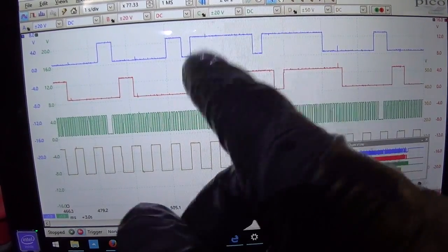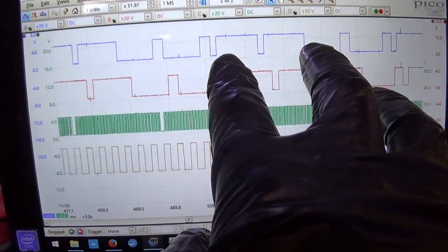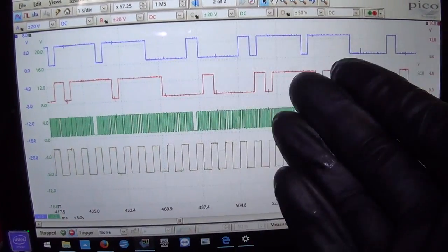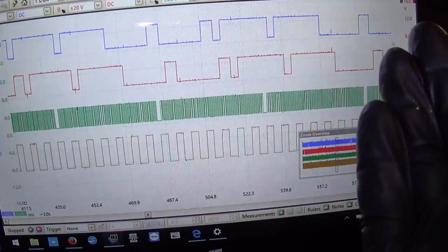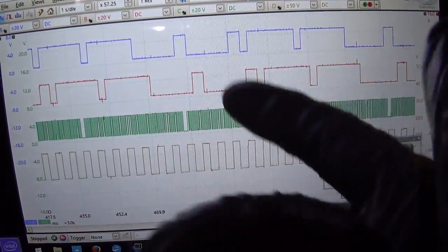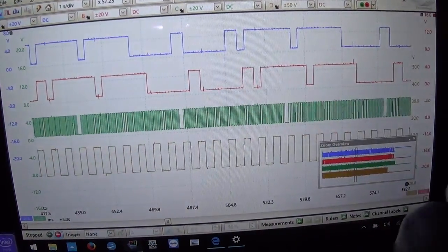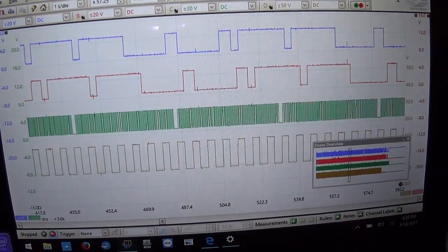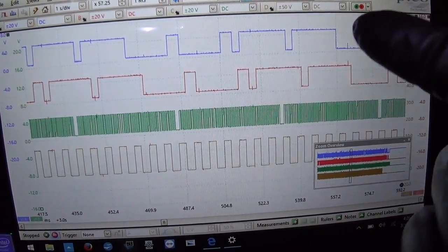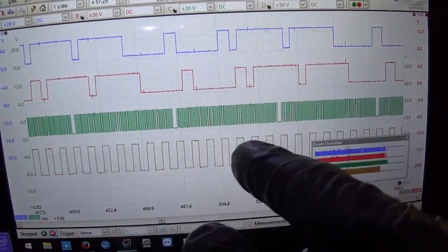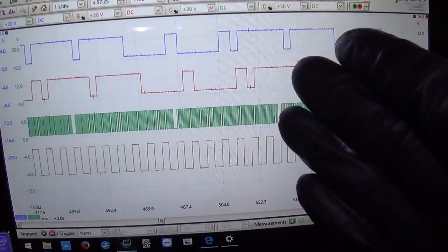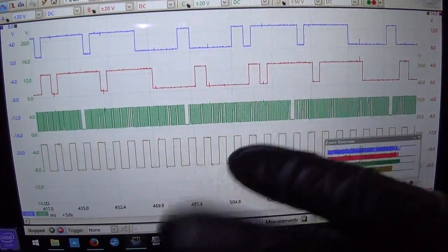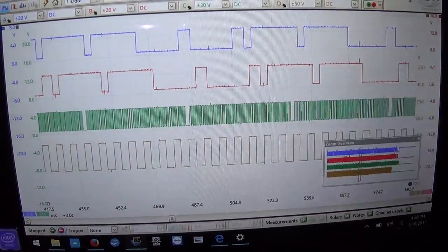So, we can get a degree measurement, like, should these line up at idle? Maybe. So potentially, this could be bad timing, absolutely. But we do know that our actual signals are good. The cam and crank signals are there, they're clean, 0 to 5 volts, and the command is there on the exhaust. So we're just gathering data here.